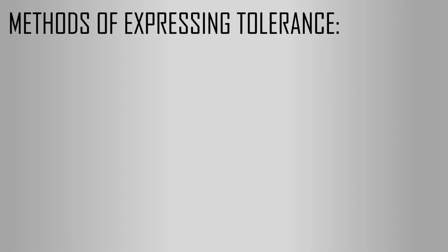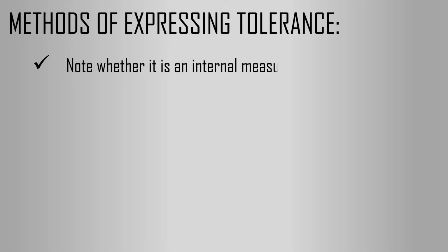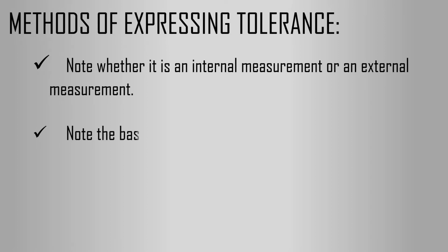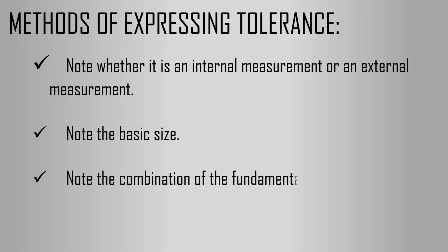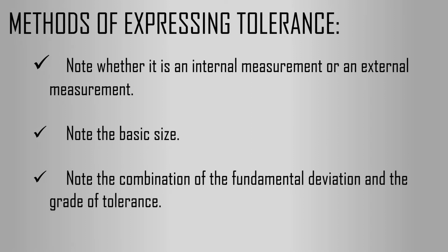And next, we are going to see about methods of expressing tolerance. The first point is, note whether it is an internal measurement or an external measurement. The second point is, note the basic size. And the third point is, note the combination of the fundamental deviation and the grade of tolerance.